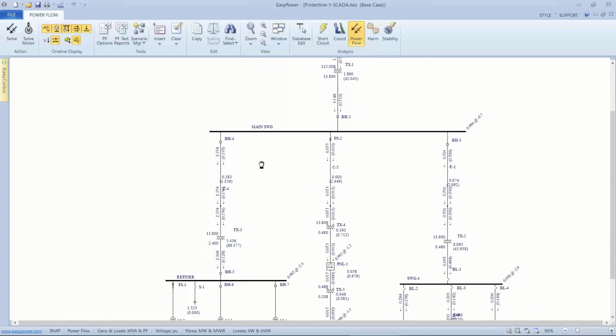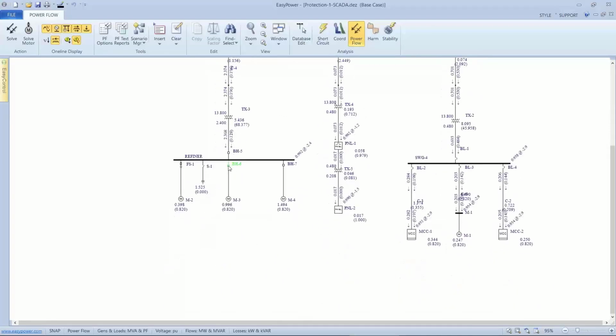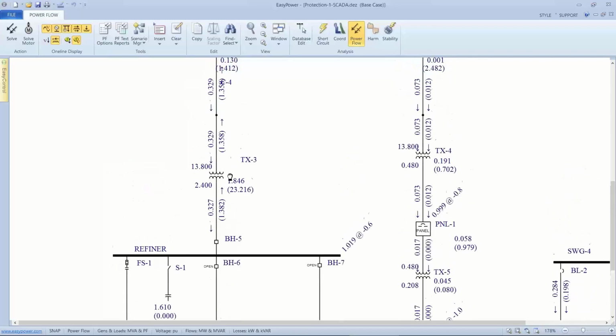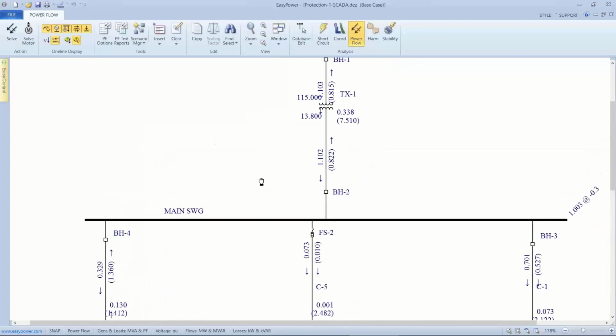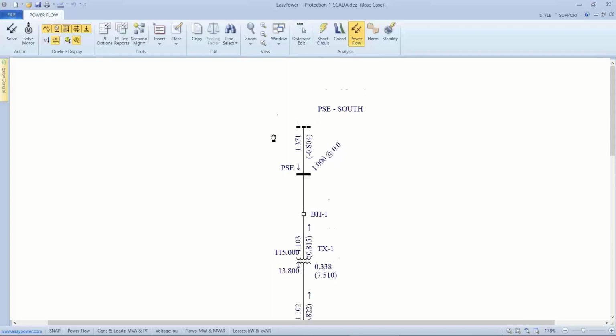But there's trade-offs in doing that. One is cost. Another is what happens when these motors are offline individually and the capacitor is still in line. And what we can see when these two motors are offline and the capacitor is still on board, that we have real power is reduced, reactive power is actually going the other way, so we're in a capacitive mode, and we're no longer leading, and we're missing the boat with utility demand factor, again outside the range of power factor.